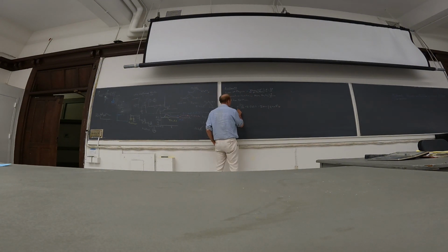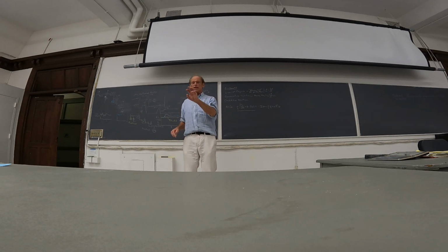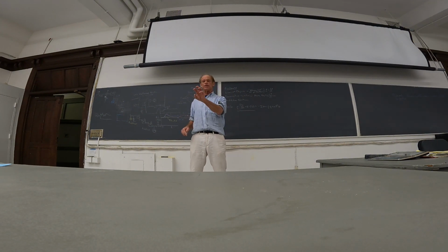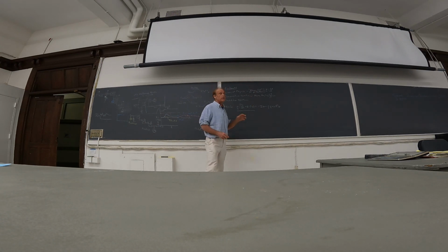This left-hand side is the mass per unit volume times the acceleration, the time rate of change of the velocity. This is the time rate of change of the velocity locally. But if I have a fluid element, it's moving. The partial derivative is how it's changing here. But that fluid element moved over here. When I go into a moving frame, this corrects for the motion of the fluid element.